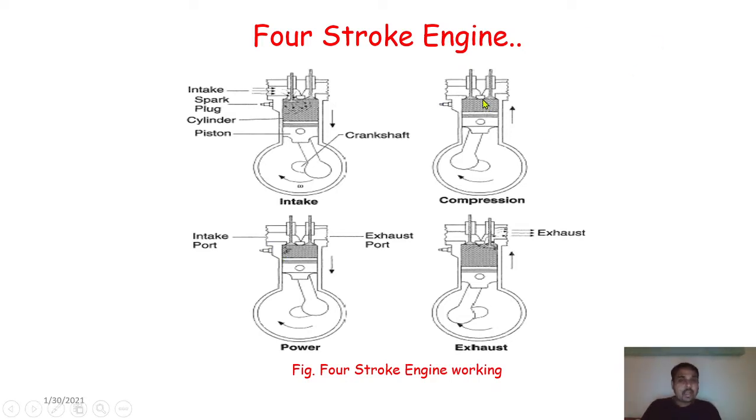Because of the compression process, the air-fuel mixture which came inside the engine cylinder during the suction process gets compressed, and its temperature and pressure increase tremendously. Inside that high-temperature, pressurized air-fuel mixture, once the spark plug provides ignition, the mixture will start to burn.